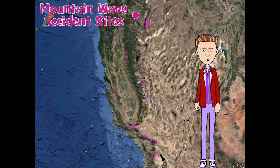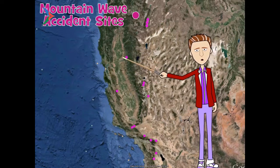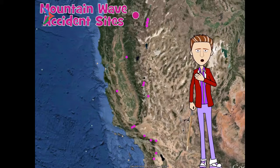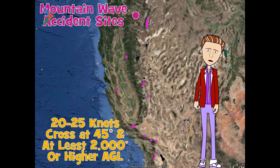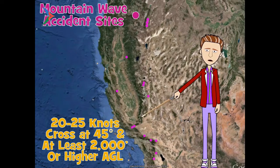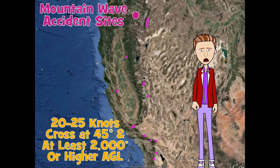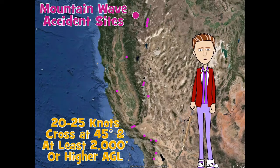Of course, if you can, it's always wise to cross a mountain as high as you can. Sure, it would be nice to cross the mountain as high as we possibly can, but sometimes that's just not a practical strategy. So if you're going to approach the mountain range, approach it at a 45-degree angle and at least cross at a minimum of 2,000 feet above ground level. And if you know the winds are blowing at 20 to 25 knots, then perhaps you'll even cross it higher while still applying the same 45-degree approach strategy.